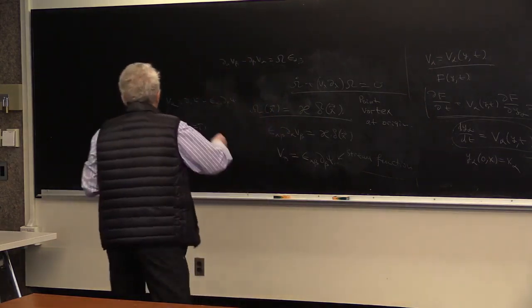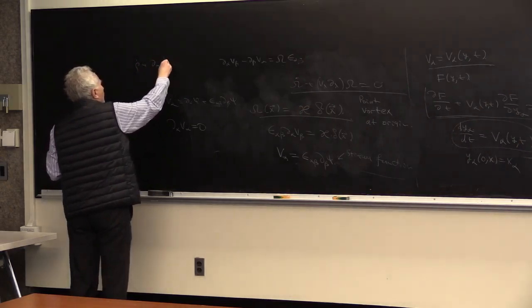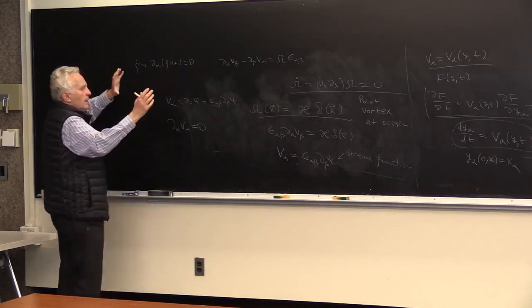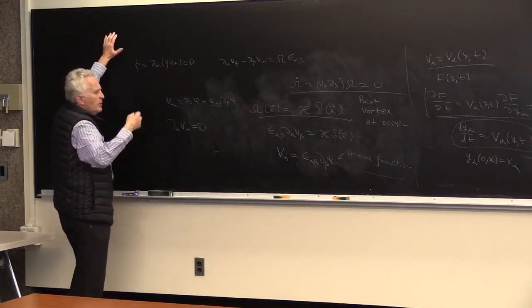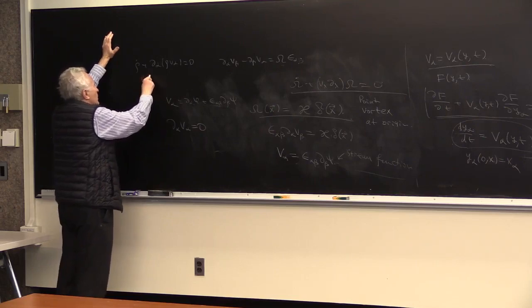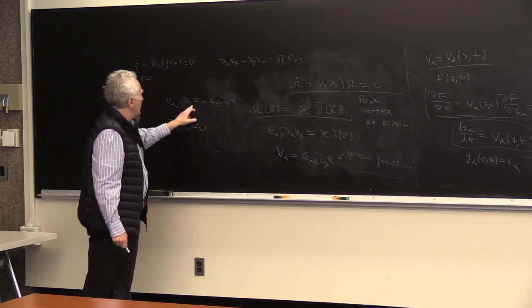That's the general continuity equation, but if you assume that the fluid is incompressible, which is very often a very good approximation, you simply set rho to 1 or some constant, and then you get the divergence as 0.